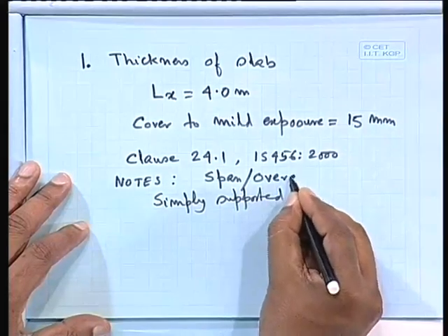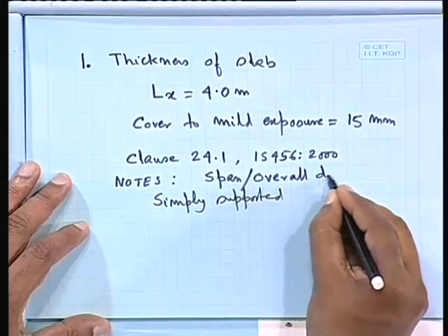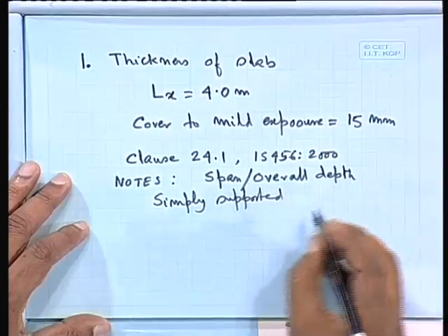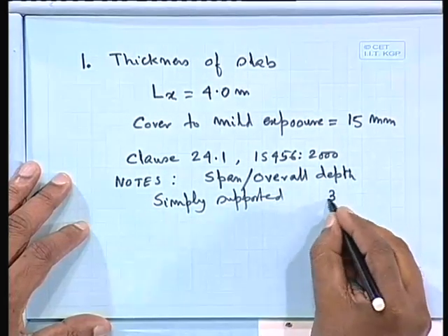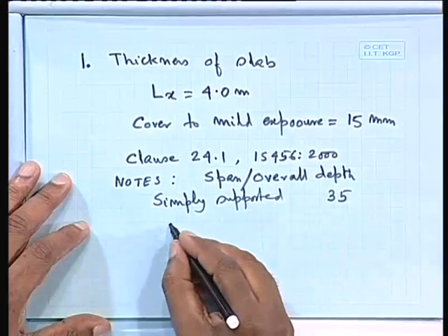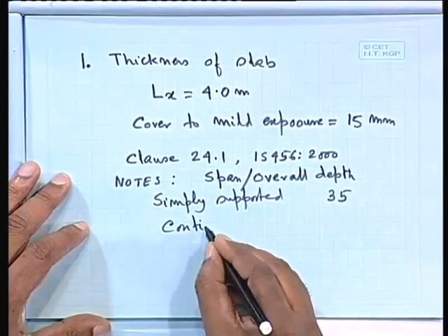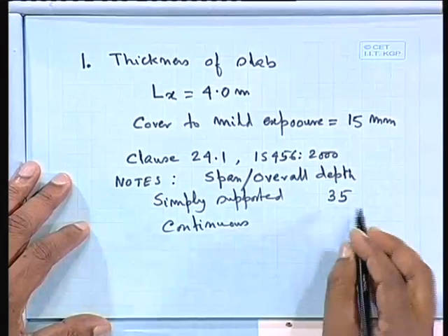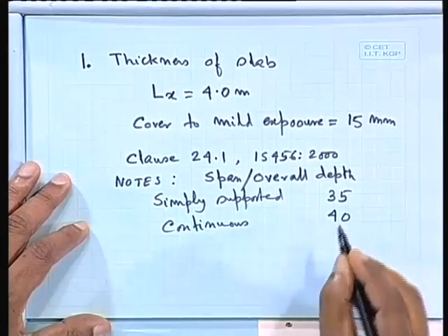Please note that it is written as overall depth. For the simply supported case, it is 35, continuous it is 40.